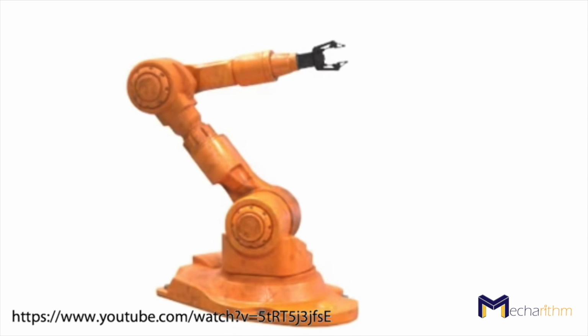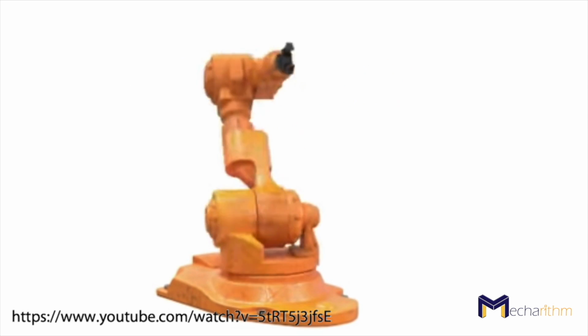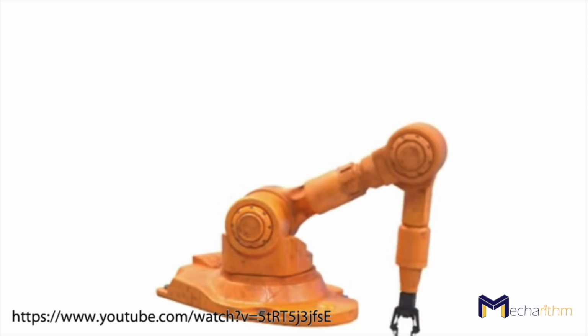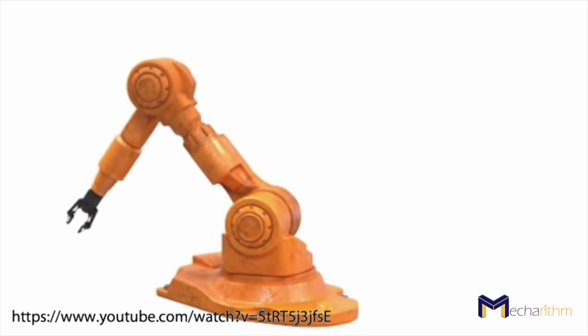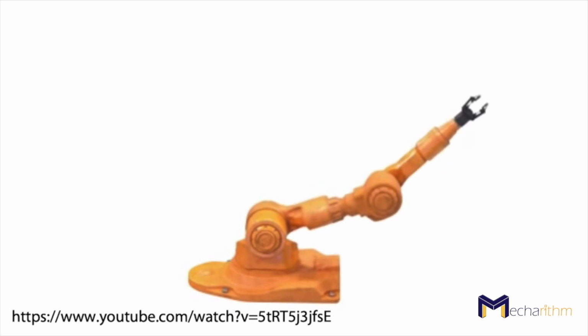The Revolute joint will put 5 constraints on the motion of 1 link with respect to the other link. So again, it will provide only 1 degree of freedom. So this 3R robot will have 3 degrees of freedom other than its end effector because it has 3 rotational joints. So up to this point, we've learned that the constraints on the links come from the joints.